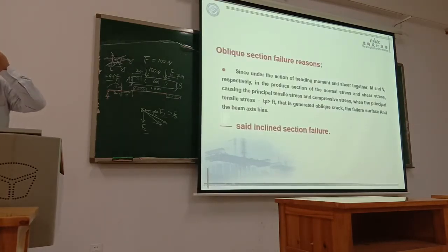So under the action of this loading, because of the internal force, we get the moment and the shear force. Once the principal tensile stress is larger than the tensile strength of the concrete, the concrete cracks. And the crack is an oblique crack.